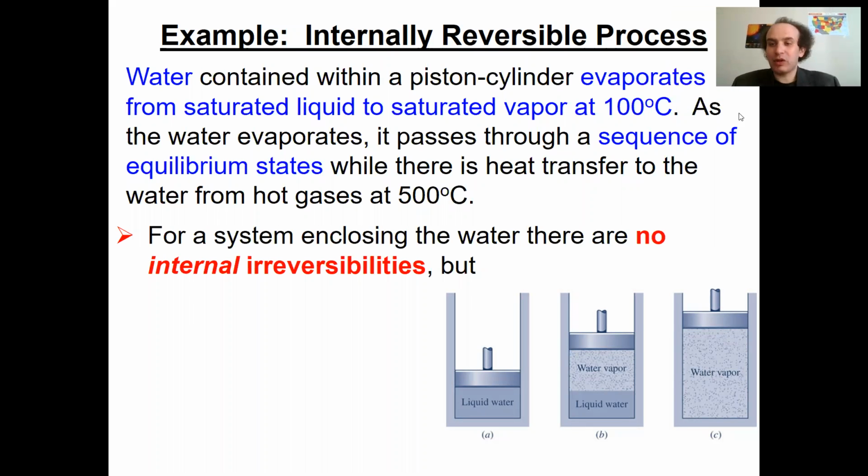And why is it important? Because this process may exist in reality. Sometimes they exist. You cannot have a fully reversible process, but you can create a system inside which, like a pendulum, you will have an internally reversible environment. So this process may exist, and you will deal with it. From the point of view of water, no entropy is generated. Entropy goes around it. That means that there are no internal irreversibilities in such a system, because the internal part of the system does not know about the stove, does not know about the fridge.